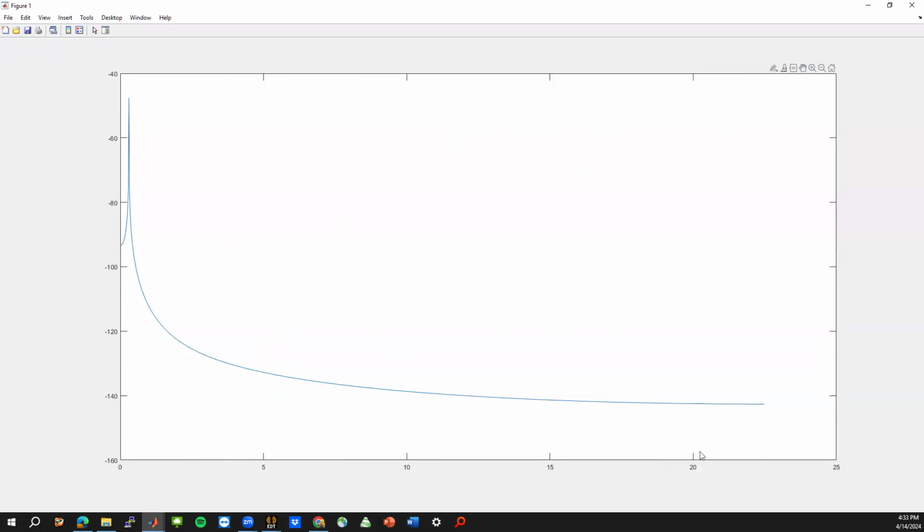Okay, and I've used a lot of points because in the measurements I'm using so many, but you don't actually have to use so many. You can just use maybe one fifth or 1/4 of the number of points that I've used here. But in general, in the measurement, I used a lot of points because there was actually a wall at some distance. So you want to make sure that the reflections from the wall don't get aliased onto your target. And that's why it's generally a good rule to use a higher number of sampling points.